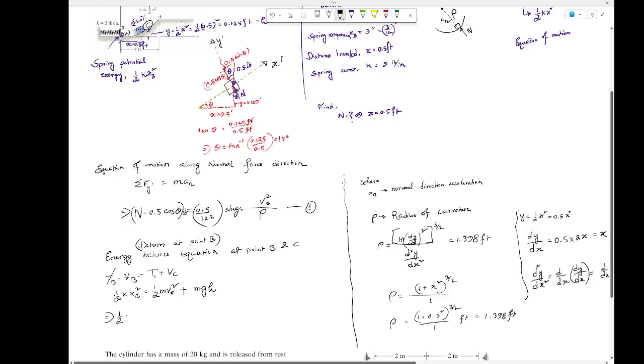So you have this half of, what is the value of the K? 5 is what? Like, 5 pound per inch, right? Are you dealing with anything in inch? No. We are dealing with what? Feet, right? So 1 feet. So that's another tricky part on this problem. Just make sure you convert everything in feet. And then the x_P is given as well, right, in inch. So you're converting it to feet.